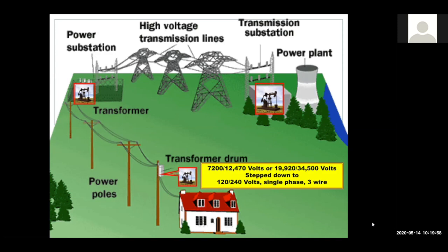Now, we have a ground coming out of that transformer that's connected to the neutral point out on the pole that goes down to the butt of that pole. It's called a butt ground, and it comes around the bottom of that pole and up the pole to the neutral point of that transformer. Then over at the house, you've got your grounding electrode, and your grounding electrode conductor feeds it. So there is actually a connection that can be made between the ground rod and over to the pole, and up the pole, back to the neutral of the transformer.